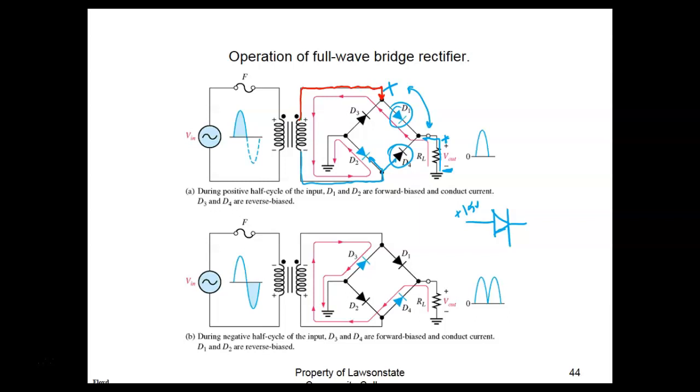Forward bias. It should measure right around plus 14.3 volts. It's got to be 0.7 of a volt less positive. And this gets people confused, and some people teach it: the anode's got to be positive and the cathode's got to be negative. And that's not true.